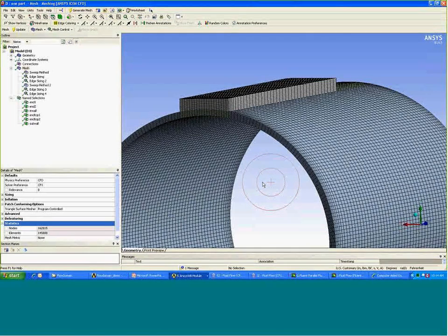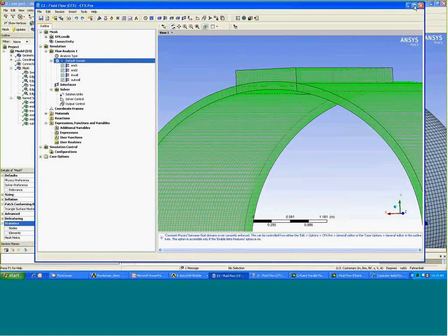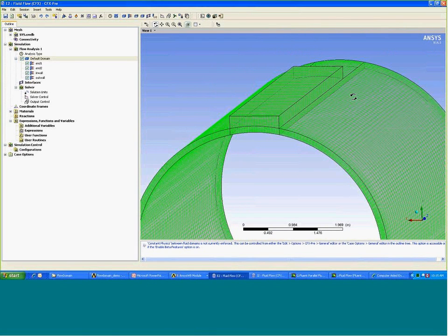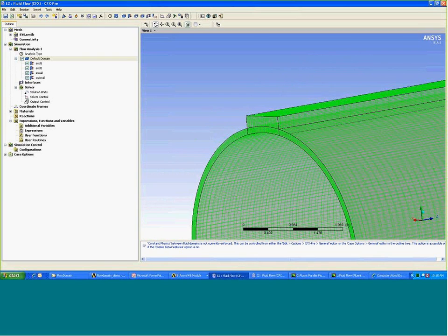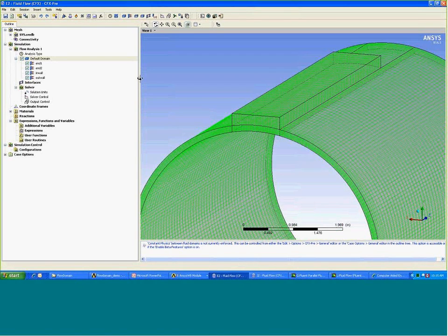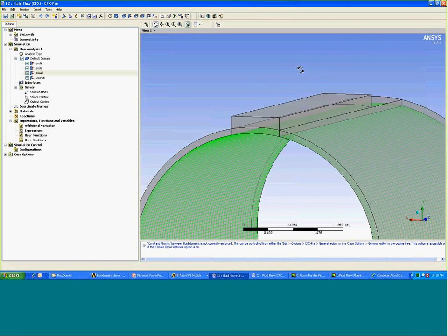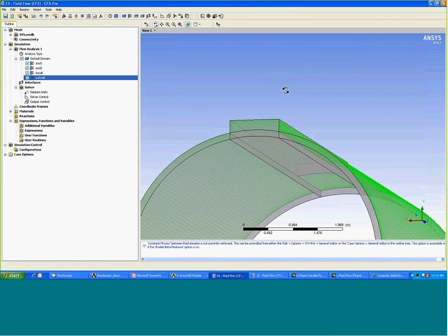Once we have the flow-through mesh, the next thing is we're going to take it to the preprocessor, CFX-Pre or the Fluent interface, to see what they're like and how we handle that. Now we have three flow volumes, keep in mind, instead of just one big flow volume. If we bring it into CFX-Pre, that's the three flow volumes and the flow-through mesh that you can see here. In here, I assign the boundaries for the surfaces. That would be the two ends, that's the inner cylinder, and this is the outer cylinder.